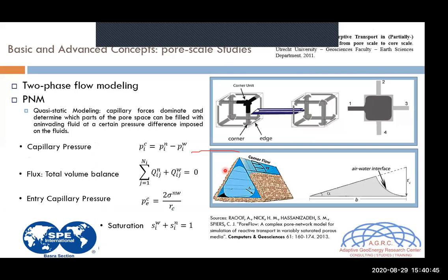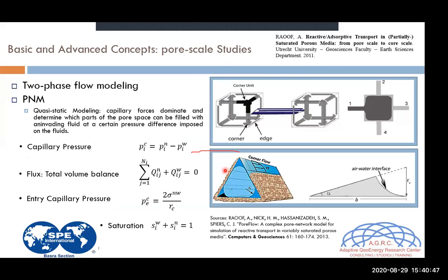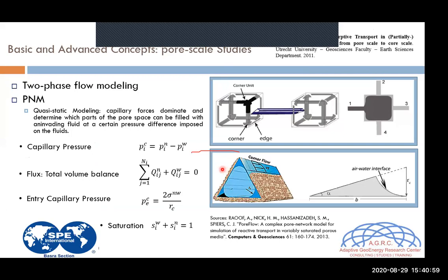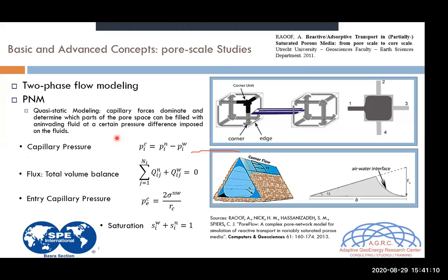Of course, as long as you are understanding your problem, you are moving to different techniques, you can improve this or that, but at least you have to be aware of what you need in all the parameters that you have to solve. Yeah? In this case here, I did a PNM-based simulation. Okay, it's a static modeling. In this case, force dominating the system, and as you can see here, we are relating this to the kind of pressure that we previously discussed. You can see this equation here, the same equation we described earlier, because in this case, in PNM, we're describing the pore body and the pore throat, and the connection between them.